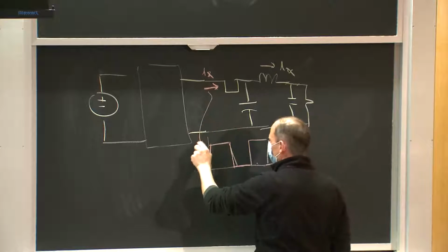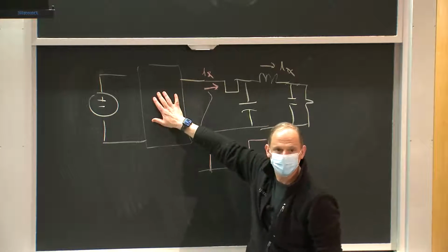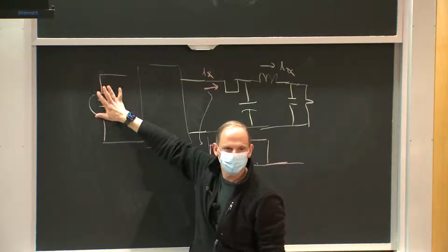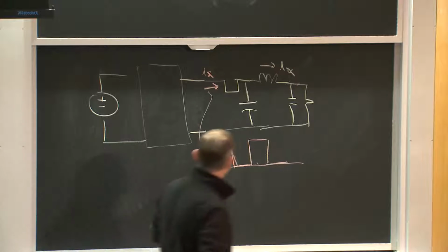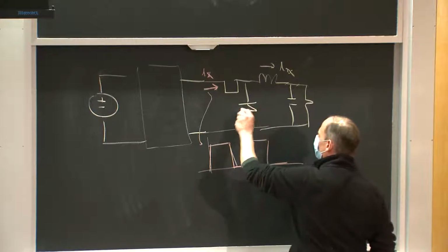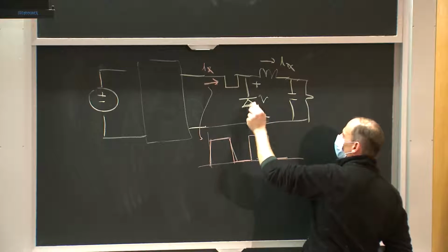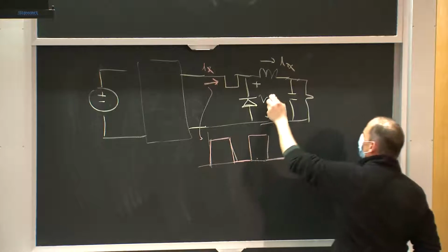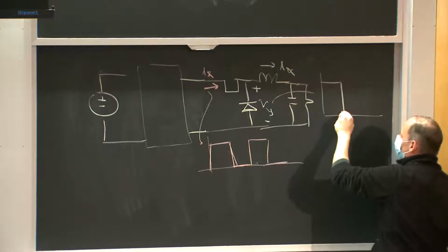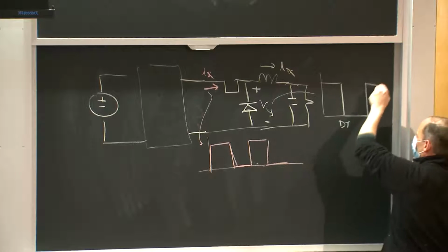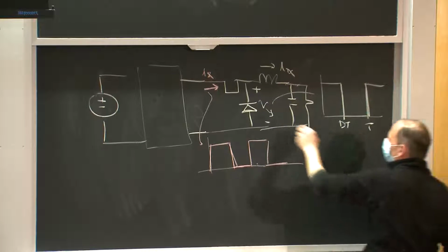All right, so the frequency content is what drives my filter, and that's what sets what shows up, say, at my input, okay? Likewise, it would be helpful if I put a diode here instead of a capacitor. If I looked at the switch voltage, let me call this V_Y, V_Y has the same sort of shape, right? I have high for some time dT, and then low for the rest of the cycle, for T. And I've got this very sharp-edged waveform right here, okay?